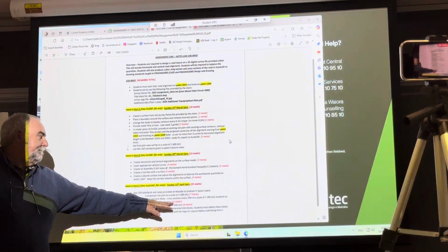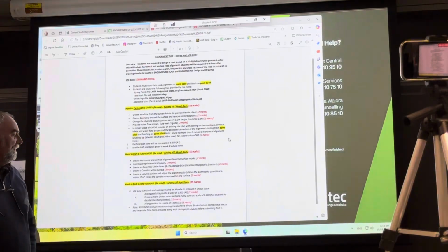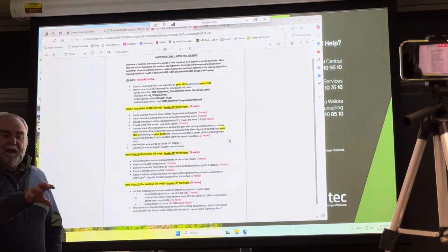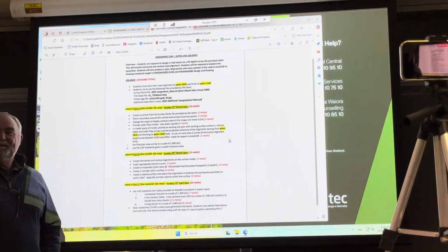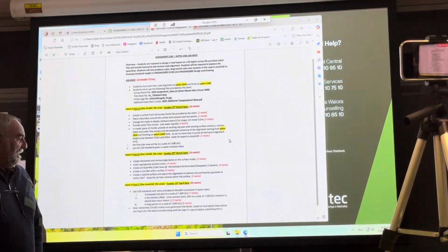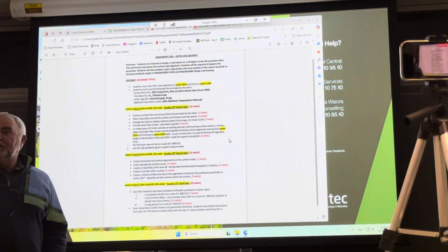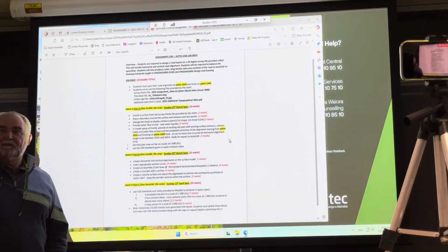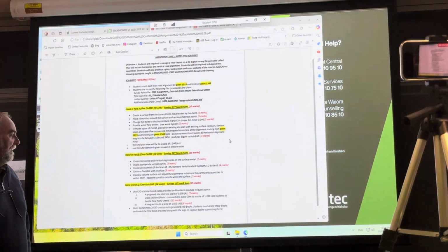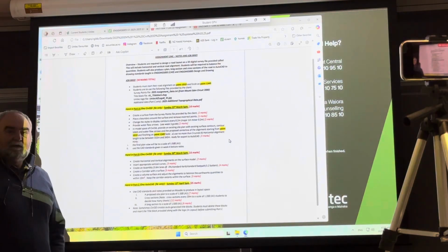That's the most marks. You just about pass this whole thing by doing really well in the cross section. So don't just go, oh, I've copied it from Civil3D. That's easy. Think about what I made you do with the cross sections last year. Long section, well obviously Civil3D is going to do all the hard work, but you're going to have to add a few bits and pieces to that too, alright? Anywhere where there's the road or batter slopes and everything needs to be labelled. And there will be marks allocated and marks off for not putting title blocks in correctly.